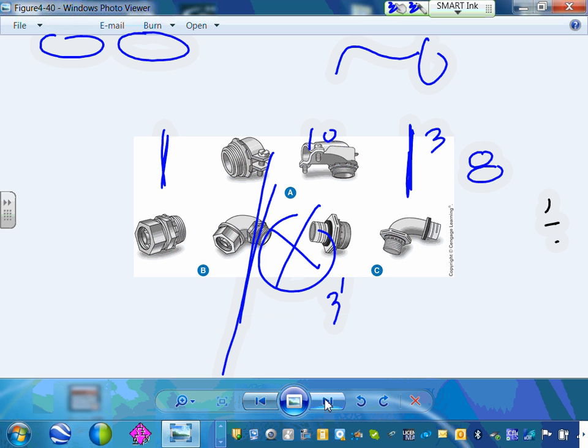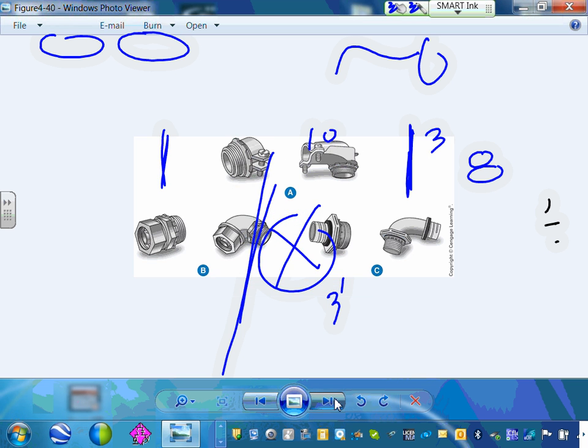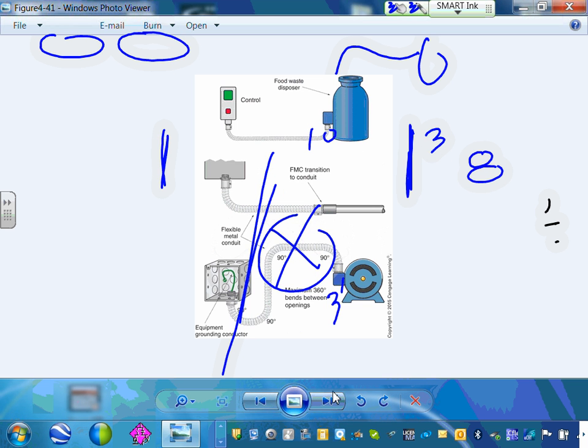Different fittings have to go with it. The fittings that go with this one are completely different than the fittings that go with the watertight. The watertight fittings have to be watertight fittings. That's how the inspector catches you. Here's a fitting; I can make this fitting work with a watertight? Well, it's a violation of the code. If this is watertight, the fittings have to be watertight. Am I making sense, knowing the hardware, the different hardware that you can use?